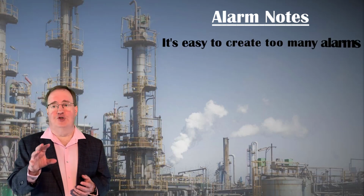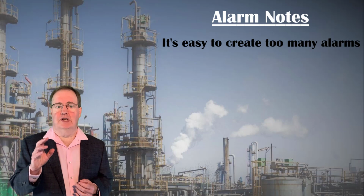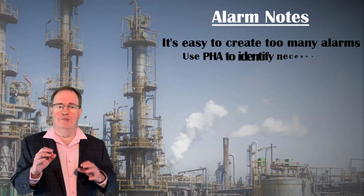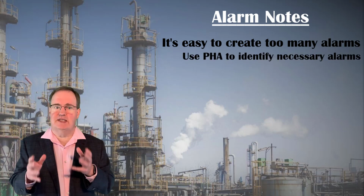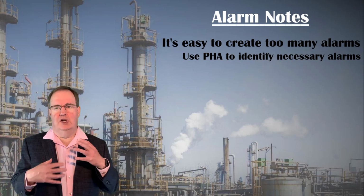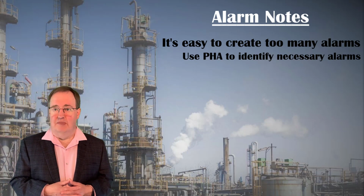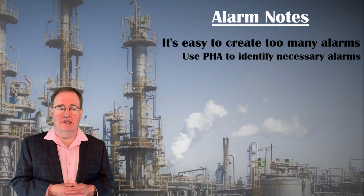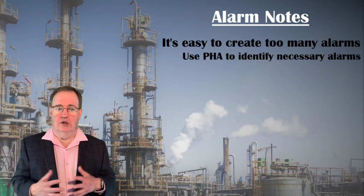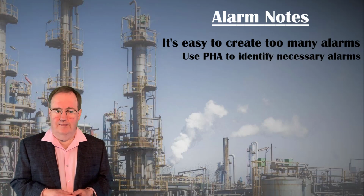Further notes on alarms. Most plants have too many alarms, which makes them a nuisance that is too often ignored. Alarms should be the product of a process hazard analysis, or PHA, where a team of engineers, operators, and other experts identify hazards, decide how to measure those hazards, and decide how the process and operators need to react when that hazard occurs. Don't just alarm everything because you can.